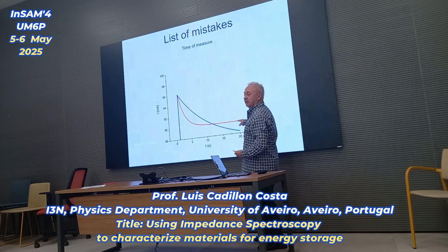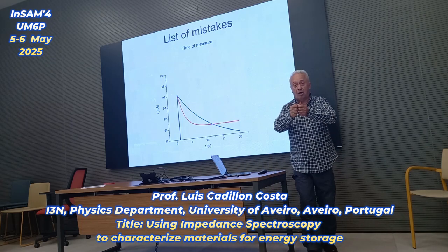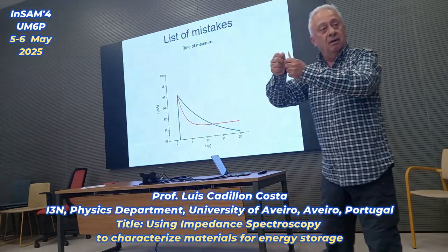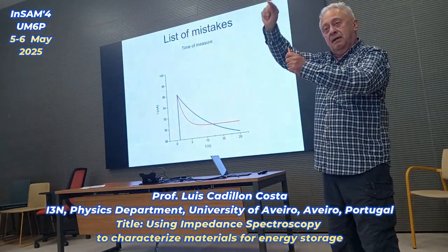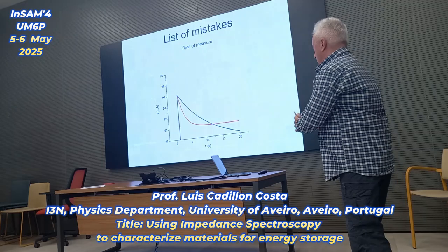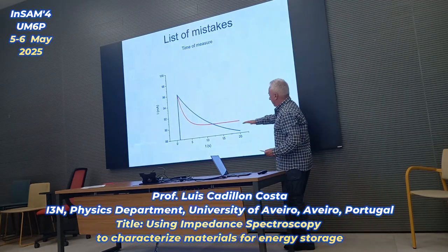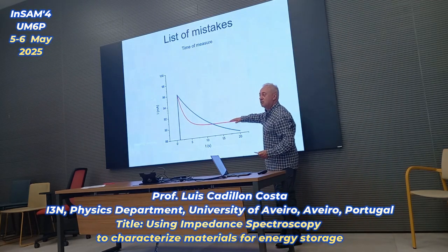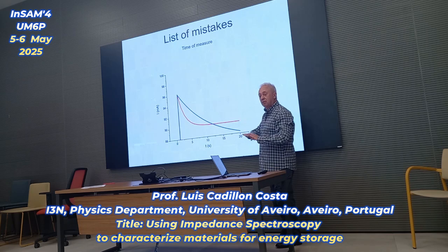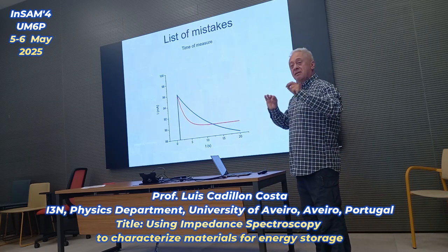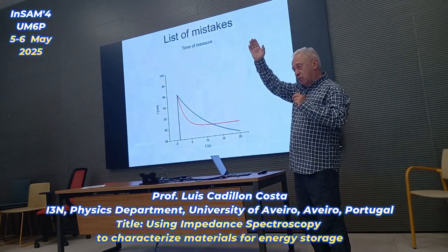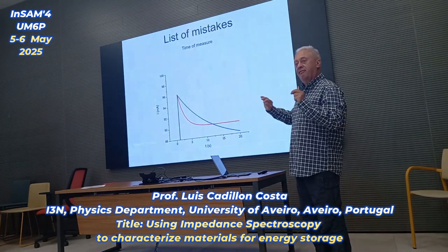If I want to measure the conductivity, I put the voltage on my sample, 100 volts, and I get a spike and then a decay, and then here I must see that the current is constant. If this is not true, which is very, very common, we must know exactly how the current decreases to attain its final value.